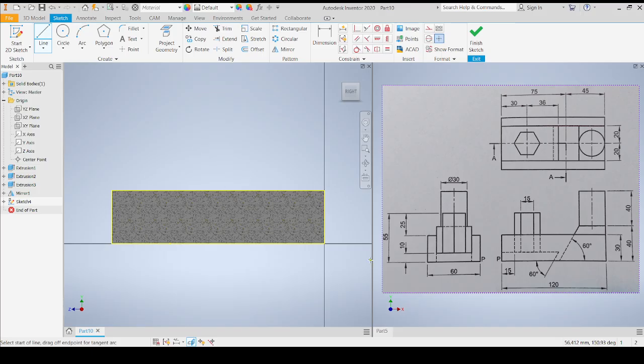So we're gonna start off our sketch. So the height of this body, it's 40 millimeters. Sorry there. Gonna make a line. Then you're gonna measure it. Gonna make it 40, right? Then the length from this point to that other point, it is the diameter. Because you can see when you project it and you take it there, you can see that from that point to that point is 30, meaning from that point to that point is diameter 30.